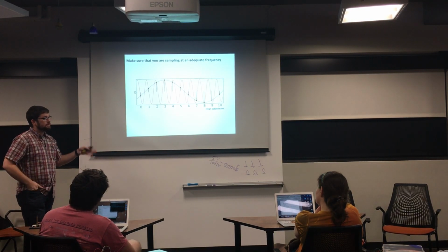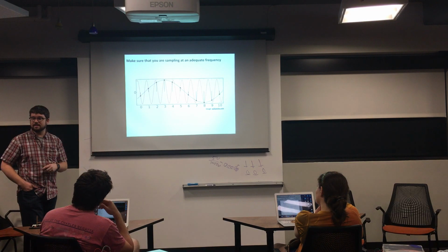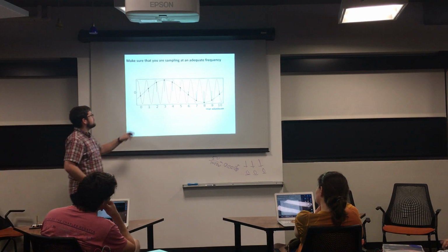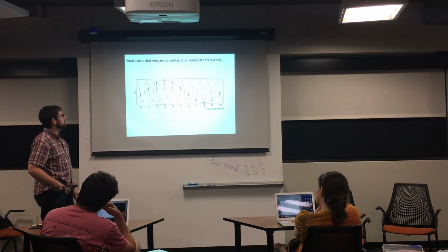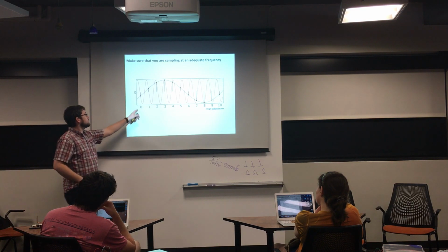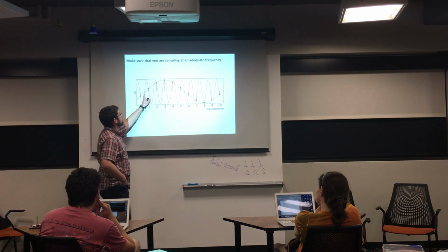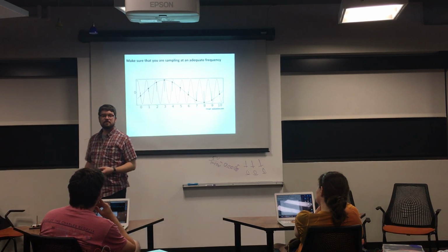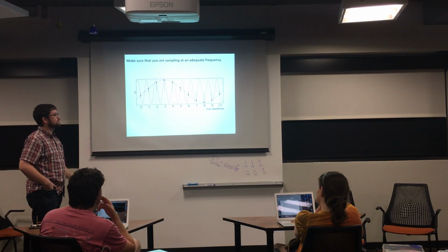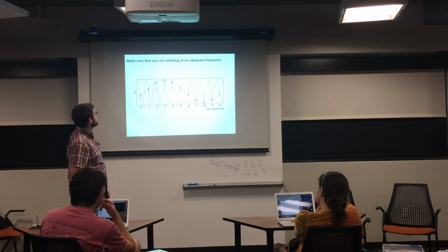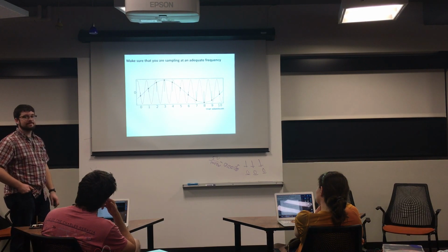And the other thing is you have to make sure that you're sampling fast enough. Is everybody familiar with aliasing? Or slightly? Alright. The idea is, let's say this red signal is our original signal. That's what nature is giving us or what our system is outputting. But we are only sampling, let's say these are seconds, we're only sampling it once a second. And so we would reconstruct this blue waveform, sampling it once a second, which is not at all what the actual system is doing. So we've completely fooled ourselves. And we're going to talk about this really nice, roughly 10-second period wave that we see in our data, when in fact it's not that at all.